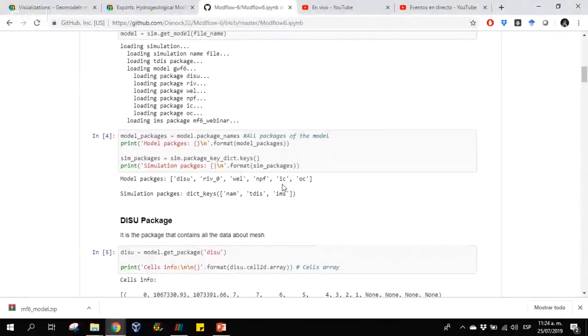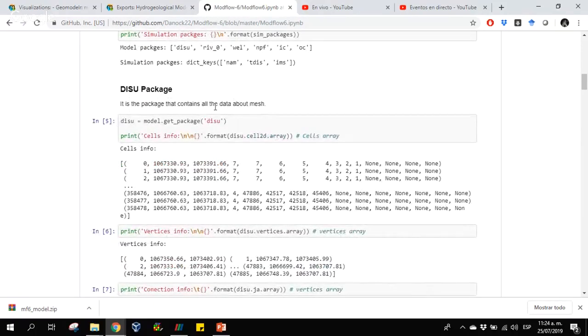It corresponds to the hydraulic conductivity, the cell type, confined or convertible, wet dry options, etc. The IC package is the initial condition package. It contains the initial head, for example, for transient models, or the initial iterative head for steady state problems, our case. And the OC package is the output control package. This file determines how and when the heads are printed. So the first one, the DISV package. If you remember, this package contains all the data about the discretization, about the mesh.